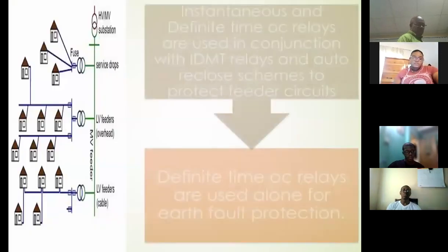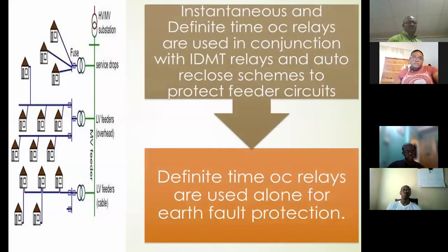So in terms of the systems of protection, as I mentioned, the instantaneous and definite time are used with your IDMT and auto-reclose schemes for feeders.